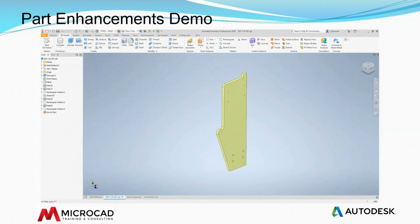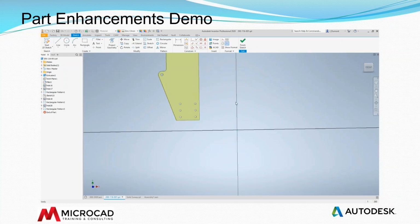So let's watch this presentation that highlights the part enhancements. This video will go over the new enhancements in the part environment with Inventor 2020. So the first thing I'll look at is in the part files in the new property panel. We'll start off with just a simple extrude command. We'll just actually select the face.